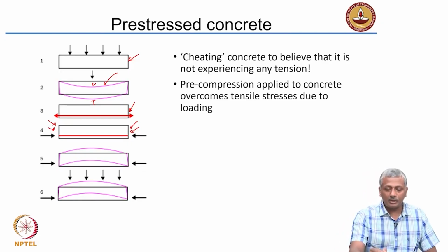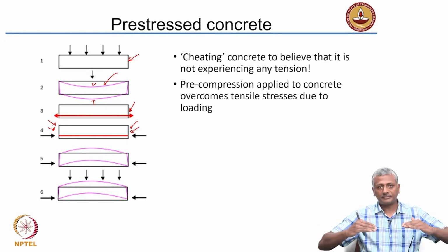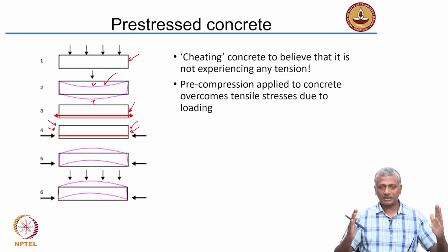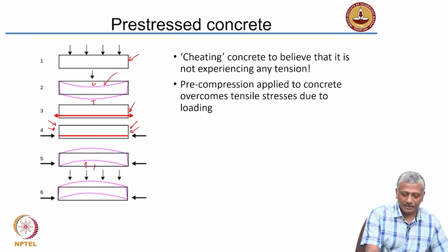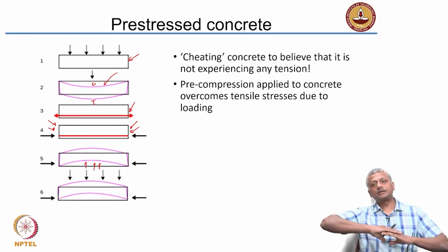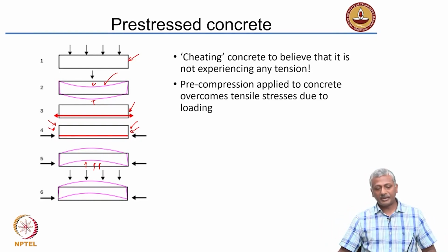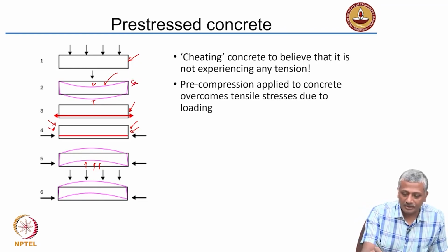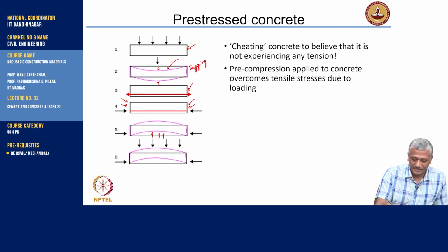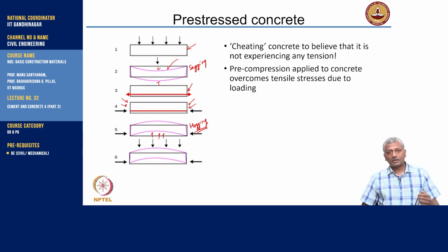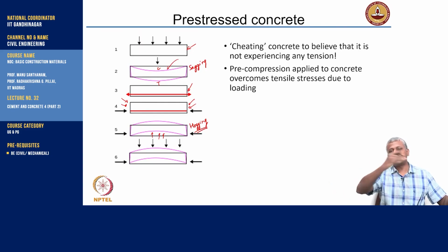So when you have the steel rod below the central axis of the concrete and you are applying this tension to the steel rod and compressing the concrete, what you will end up doing is causing the concrete beam to bend upwards. Concrete beam will bend upwards. So this downward bending is called sagging. This upward bending is called hogging. So now what is going to happen? This concrete beam, even before it's actually loaded in the structure, has now bent slightly upwards.